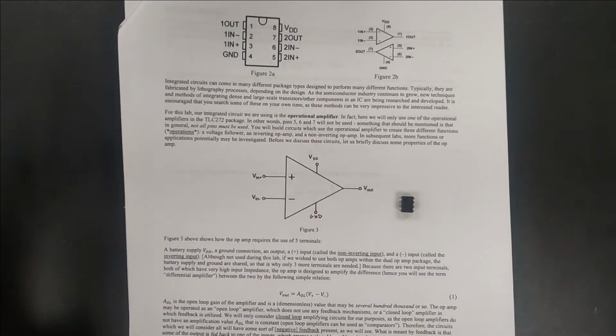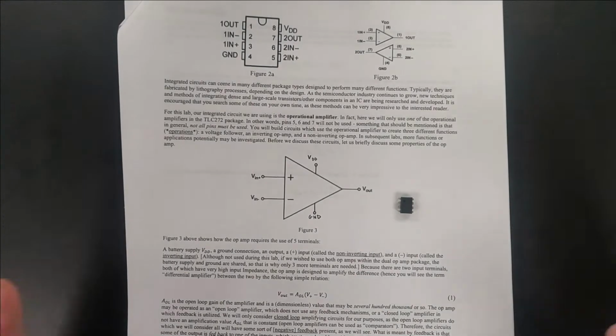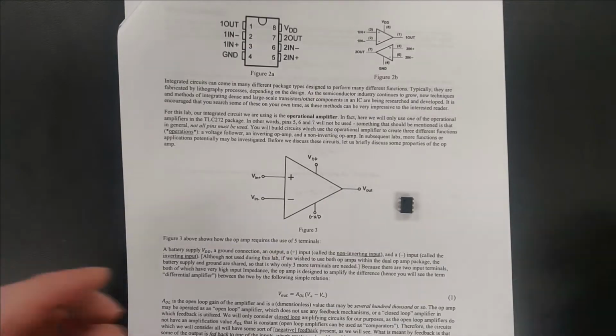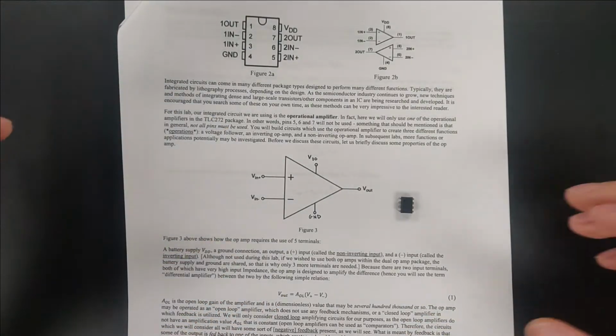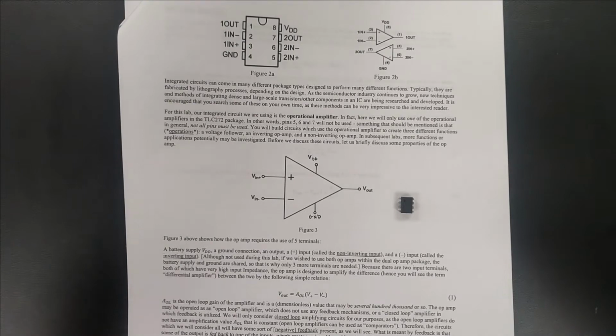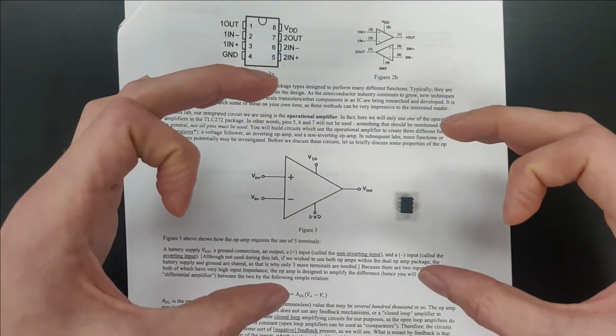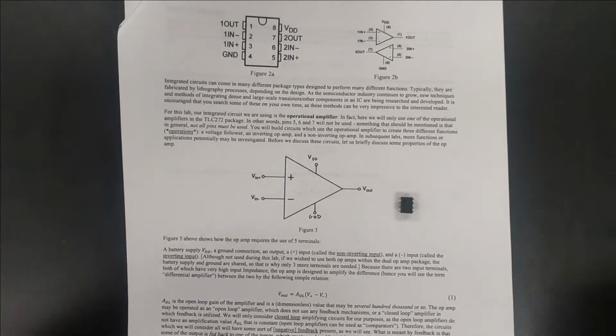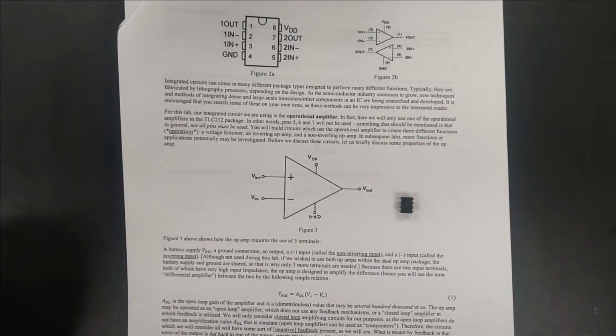So we're never going to exceed 10 volts for this circuit, because it's not good for it. All of our amplified signals, whatever they are, are going to need to exist within this 10 volt max range. So it's an upper limit on how much this op amp can amplify a signal.